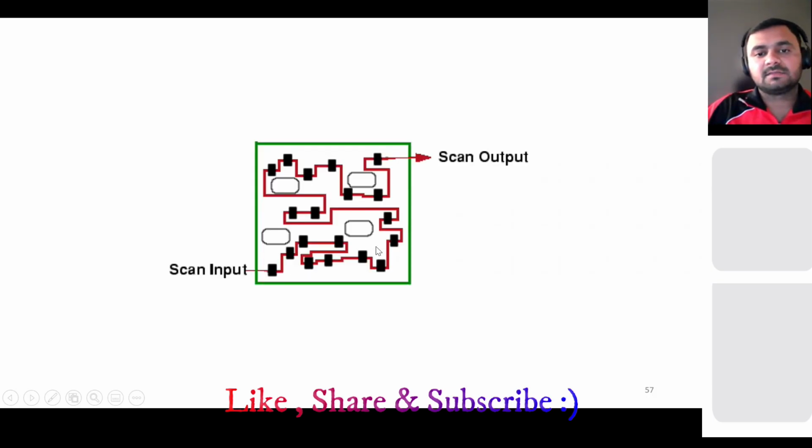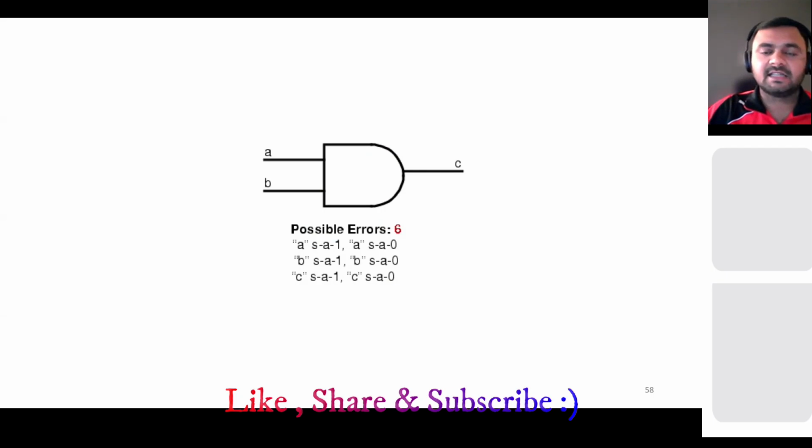Basically, flops are nothing but logic gates, AND gate, OR gate. If you open that, ultimately these gates are nothing but transistors, the NMOS, PMOS transistors and their connectivity. So take this AND gate, suppose this A input is stuck at 1. You can see here SA is stuck at 1, stuck at 0. Suppose in a chip, this gate is stuck to VDD.